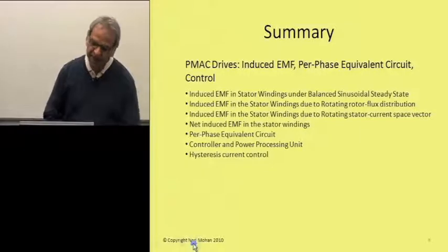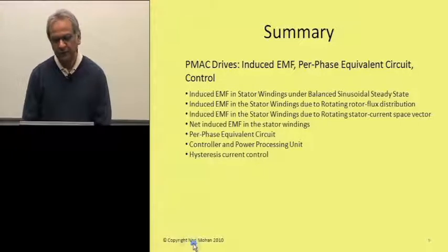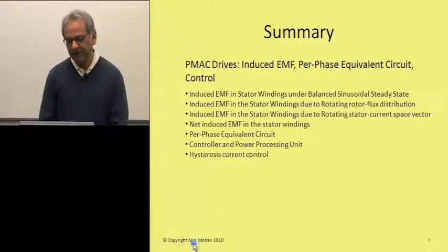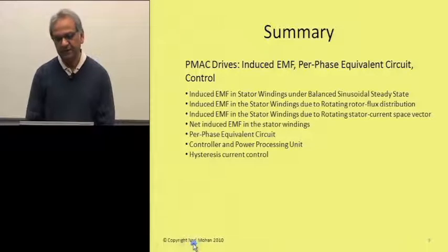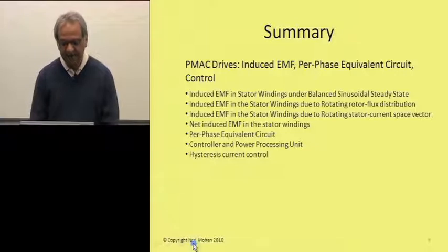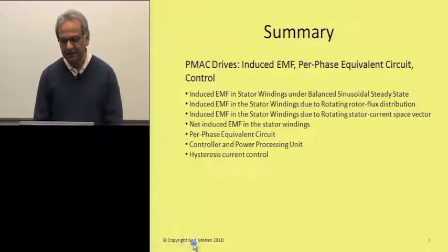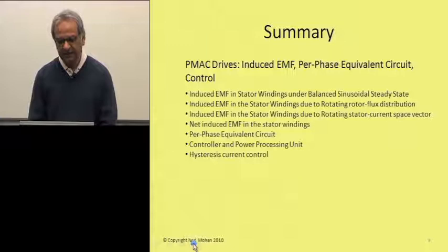So here we have a very brief summary of what we have seen in this module. First of all, we have induced EMFs in the stator windings, and we came up with the per phase equivalent circuit. Then we saw how we can supply, at least in a very simple, perhaps simplistic manner, currents into these three phases of this machine.